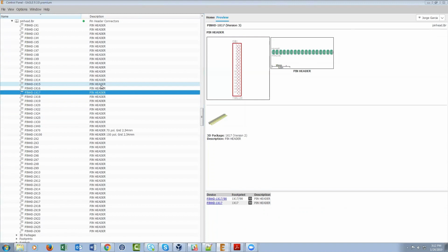Also, this is great, but it doesn't allow libraries to. Okay, yeah. Jumping back to the crystal design, the part seemed to be floating above the pad. The reason it was floating was because you entered the width of the component instead of the thickness.